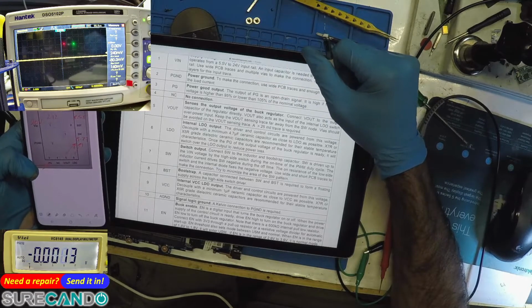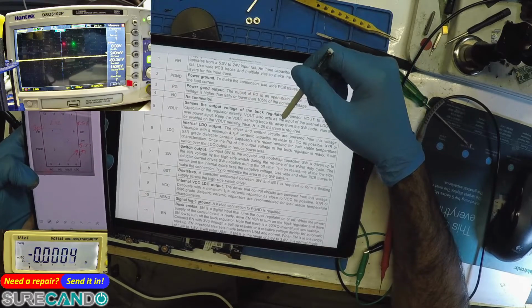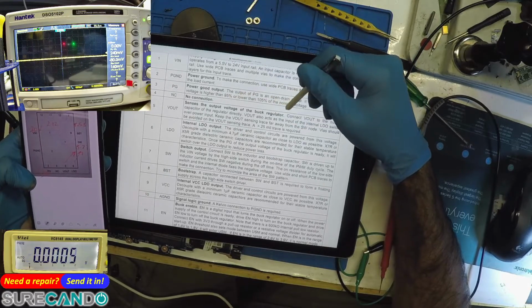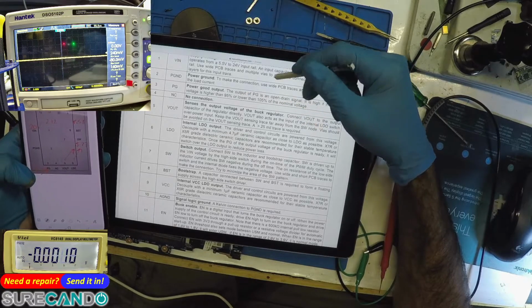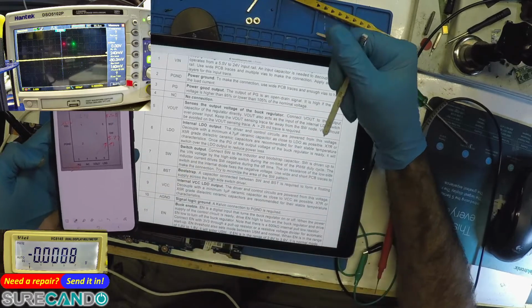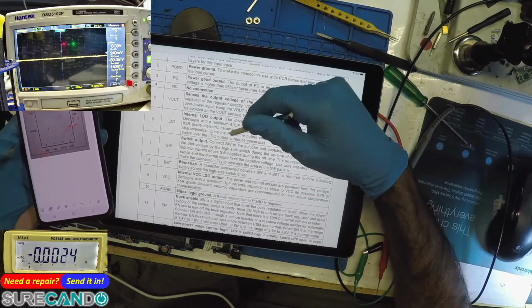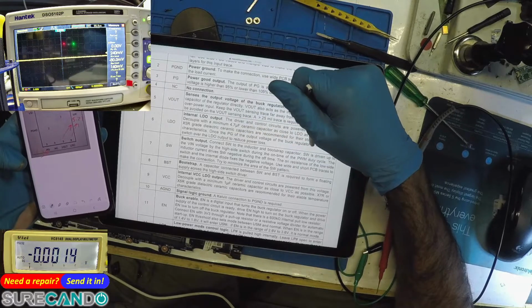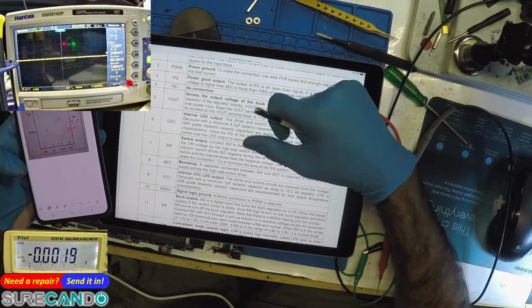It is high if the output voltage is higher than 95% or lower than nominal voltage. Okay. So it's staying low, so that's fine, I guess. Okay. Once the power good of the output voltage of the buck regulator is ready, it will switch over the LDO output to reduce power loss.